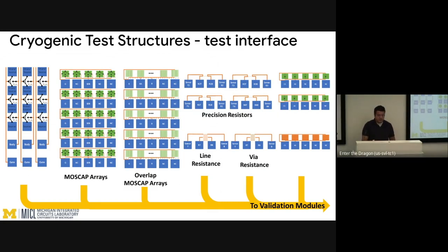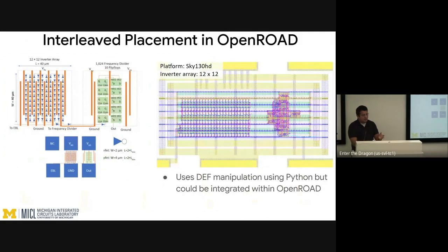And then that's where we discovered this could be very useful to our other generators, like a PMU, which has a lot of flying caps, switches, power switches. That's very useful for ADCs as well, DACs. So I think this is awesome because you can also integrate some of these customized blocks with a cell-based approach, and then you have a diminishing return rule here where you don't spend a lot of time on the part that doesn't require attention, but then you spend some time writing some Python scripts for the blocks that require attention, like a DCO for a PLL, flying caps.